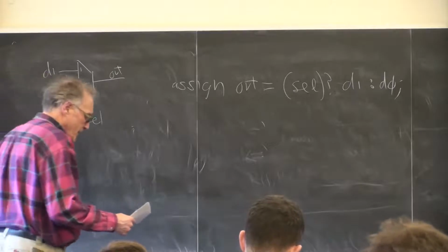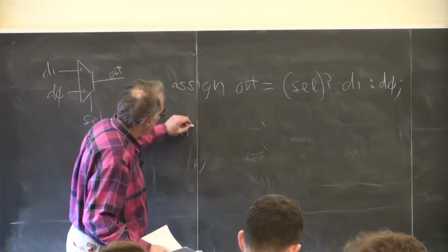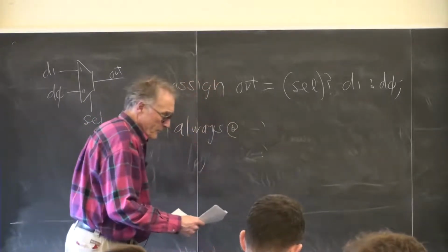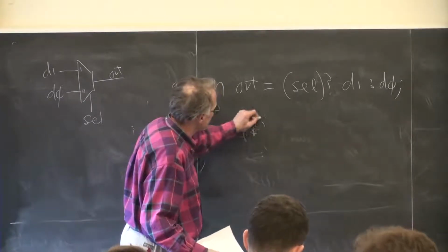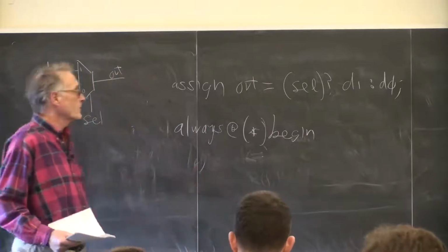The second way would be to use an if statement. So you could say always at, and what I'm going to suggest is always use star, because that's the only thing that makes sense in synthesis.